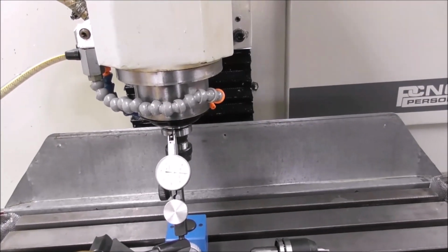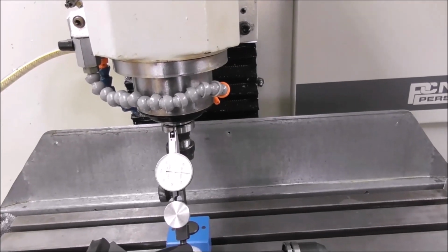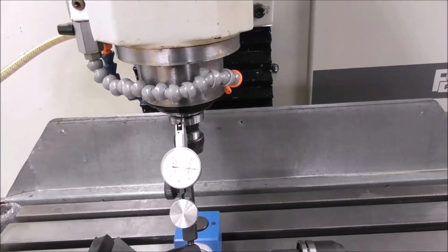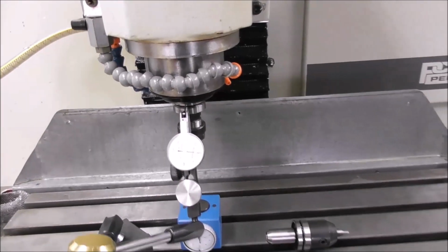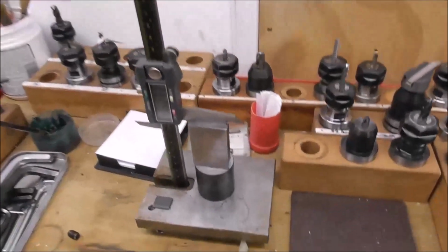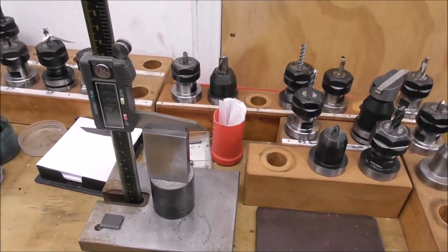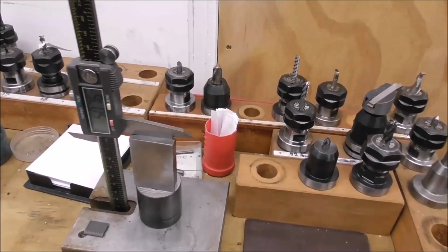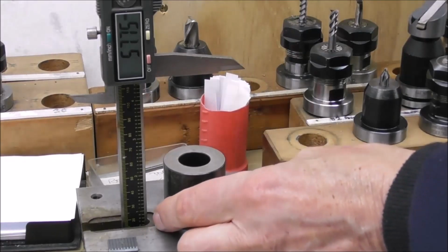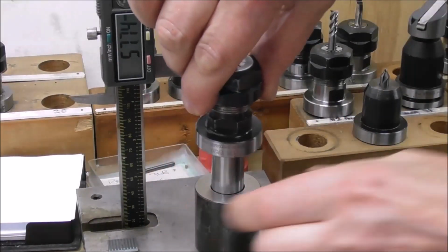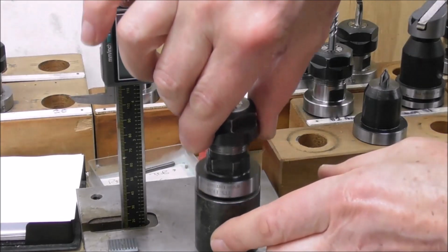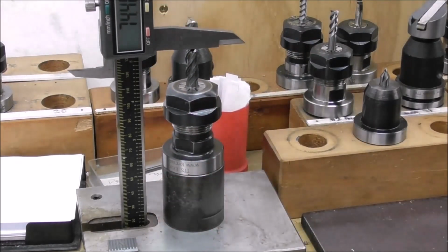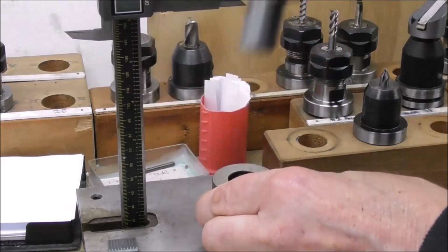If you're measuring your tool length off the machine with a separate system, you can see there's an error there of around about a thou. Then if you're going to be measuring it with something like a digital height gauge, there's likely to be errors in there as well. I've just put the camera on a tripod again to show you another issue. If you're measuring your tools off the machine, you'll likely be using something like this, or a hole in your surface plate, and coming down with a digital height gauge. But there's errors there as well.